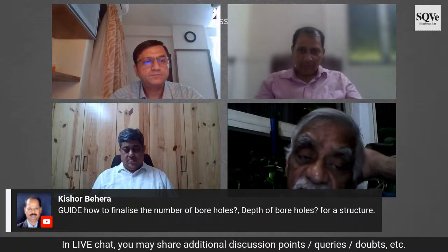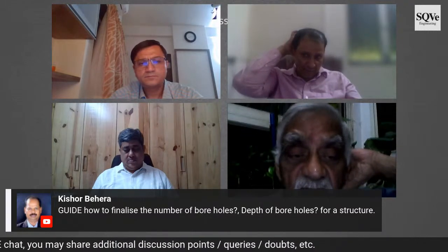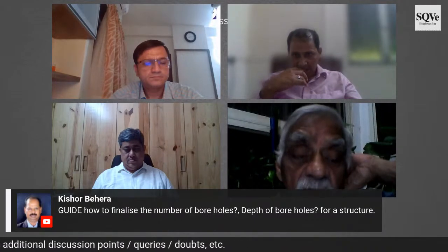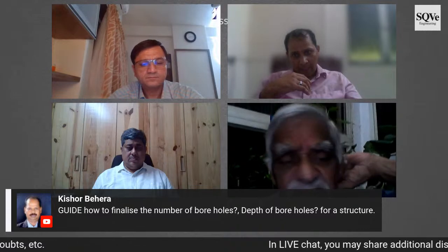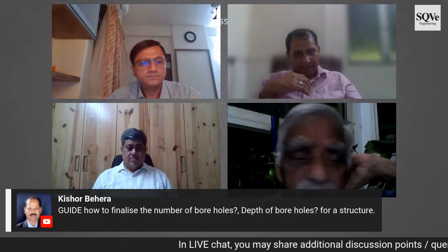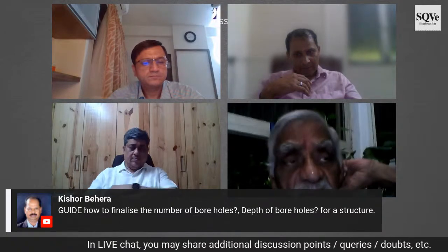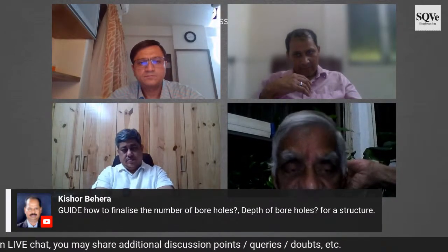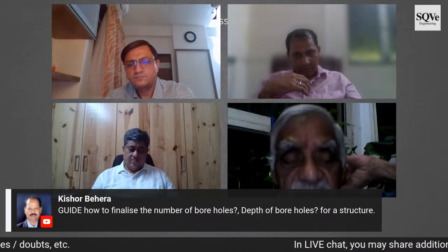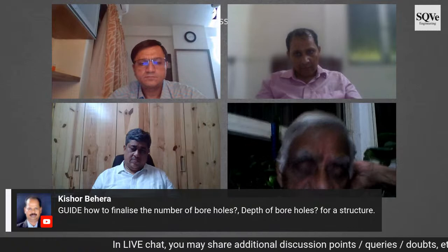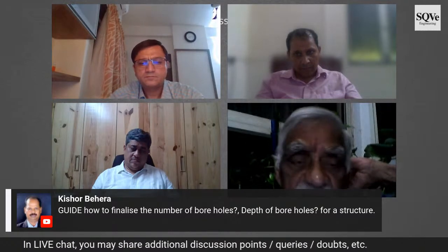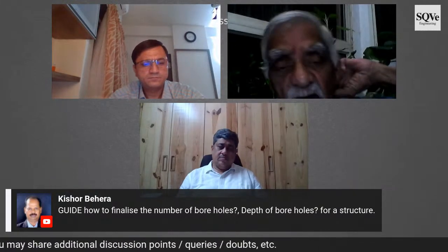Similarly, when we were doing work in Kakinada, a lot of details were available from the adjacent sites. Or in Noida, or anywhere else, whether in Malaysia or Moscow. So you get initial data and make an assumption, which is certainly not accurate, but quite a few times, based on this data, we could say what the bearing capacity or bore log would probably be.